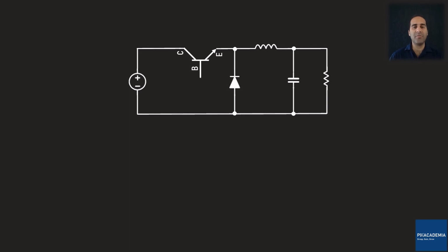Since the doping concentration is disproportional to the collector-emitter breakdown voltage, the doping concentration needs to get reduced. This, in turn, affects the BJT current gain. Although the breakdown voltage gets larger when reducing the doping concentration, the BJT current gain gets smaller.